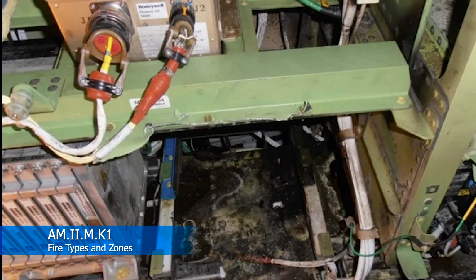Now, out of all the different types of aircraft fire, this is the one that I've actually seen the most of for sure. The one fire that always comes to mind was on a KC-46. The guy didn't tighten down power feeders. They were right about the same place on the ERAC, at the center line, one of the big power feeders to come off the battery, and the two that come in off the engine. He didn't tighten them all the way down. He didn't torque them correctly. That caused the lead to sit cockeyed and not fully connect or fully touch the rest of the post.